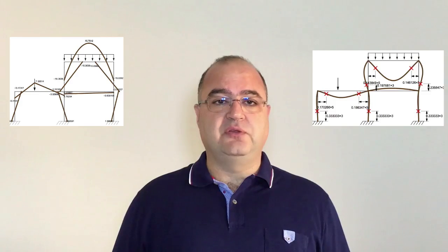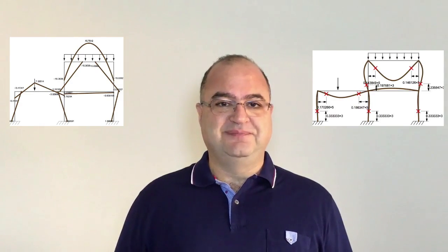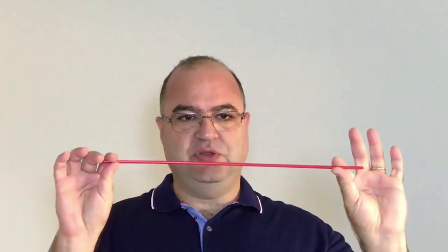I will explain two core concepts and show how to use those to step-by-step approximately analyze a simple example. By analyze, I mean sketch the deformed shape with the approximate location of all inflection points, and sketch the bending moment diagram with approximate value for all the internal moments at key points. We start with one of the simplest configuration, a simply supported beam.